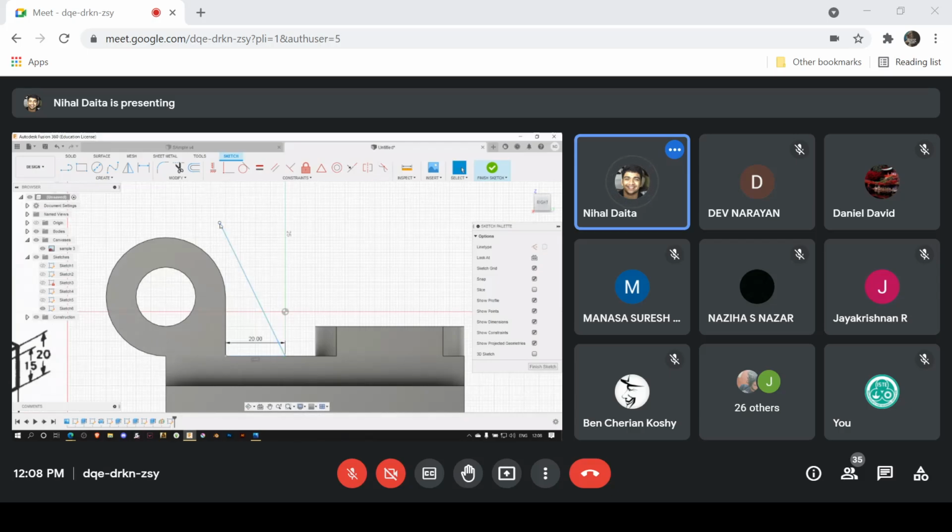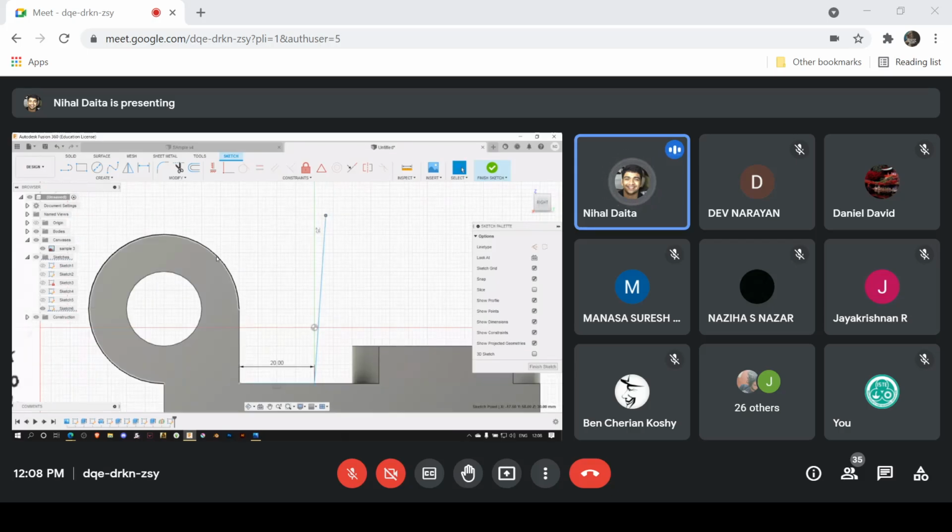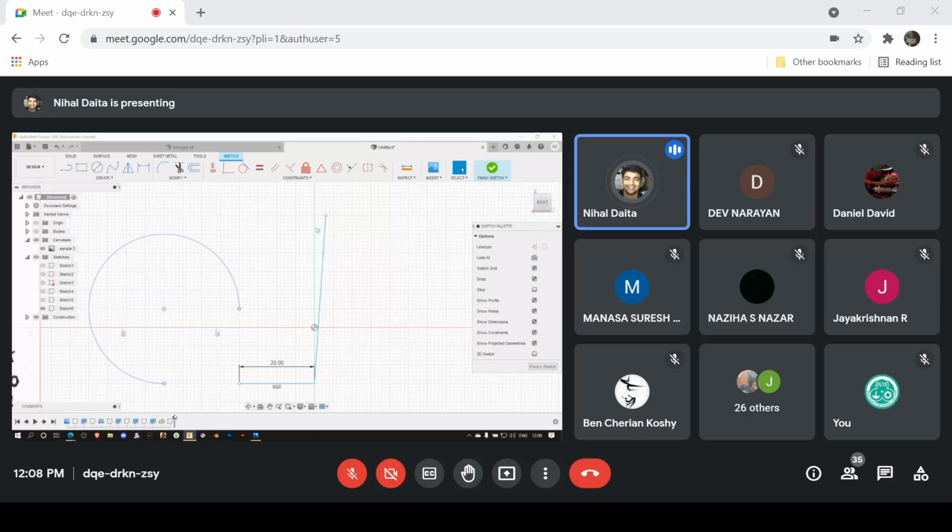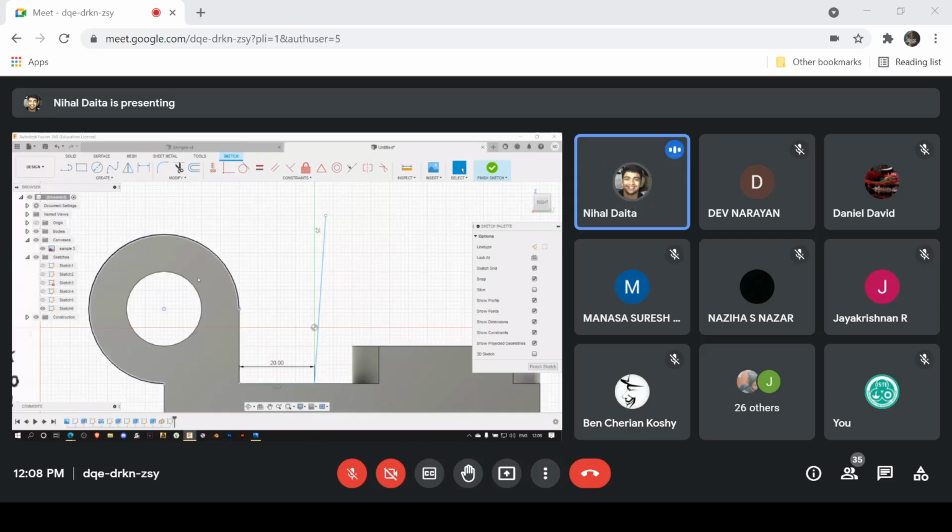Let's say there. So can I actually drag and move this line, right? One way to make it tangential is to just ease along the surface. Okay, so here we definitely need to use the project one. I need to make it tangential to this particular curved surface, right? So I select the curved surface, click P to project and click OK. As you can see, there is a violet line projected on. I can just remove the body and I can show you. See, the violet line denotes that particular curved surface, right? So now I can simply drag this and slide it along until it centers.